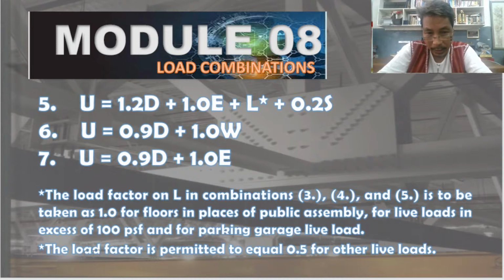For other types of live loads other than the mentioned conditions, we can put 0.5 load factor instead of 1. Take note of this.